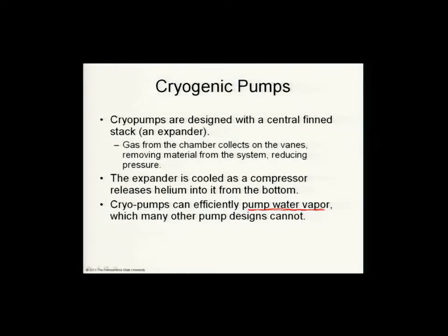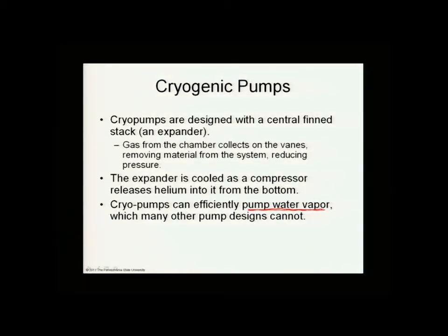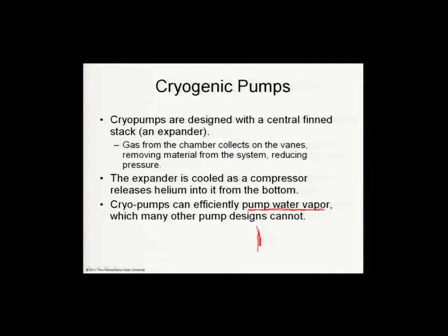And water vapor can be hard to pump because water molecules are pretty light, and so it's tough to change the momentum. And changing the momentum is what a mechanical pump does. It's what a diffusion pump does. But we're not relying on changing the momentum in a cryopump. We're relying on getting them to stick to a surface by van der Waals forces. And so cryopumps are very, very good at pumping water vapor.